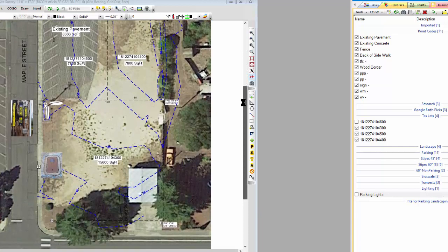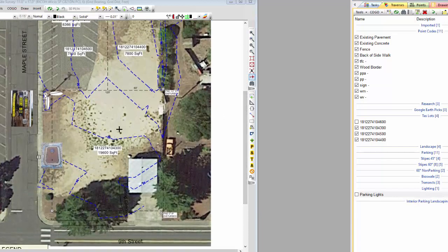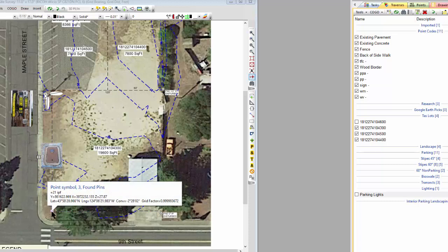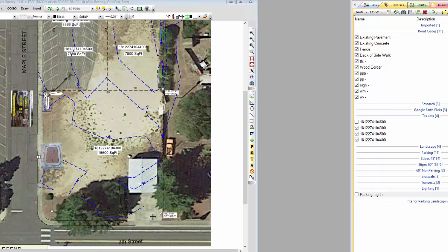I started out with just a Google Earth photo, and I'm working in state plane grid coordinates. So I brought the photo in from Google Earth, and all I had to really reference was the center line of some streets here. It turns out the only thing I have out here to hang my hat on is one iron pipe down here in the southwest corner. I found some other monuments, not of record, that were laying flat 4 feet under the ground. So I don't have a lot to work from other than the street alignment. So the photo that I picked was just fine.